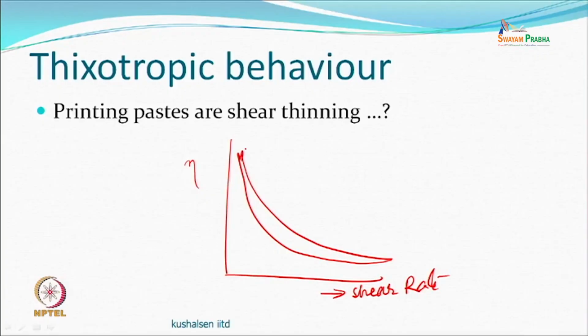Similar is the case of melt spinning or wet spinning. When polymer solution is pushed through the spinneret, the viscosity around the spinneret and through the hole becomes very low and just passes through that. And after that, of course, there are other processes with which it solidifies. So our aim is different. So this thixotropic behavior of our printing paste is an important characteristic of the paste. Any polymer which does not give us this is also not so good.